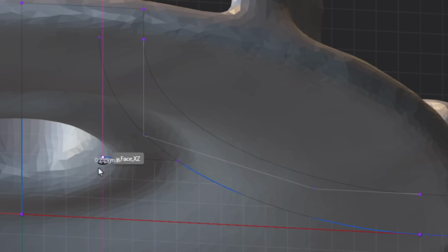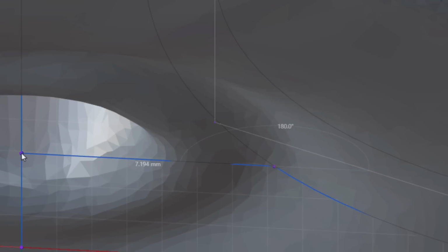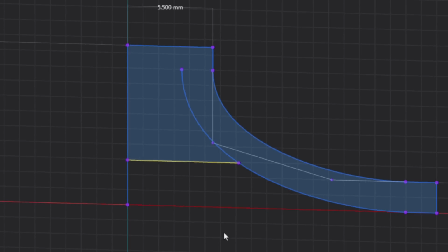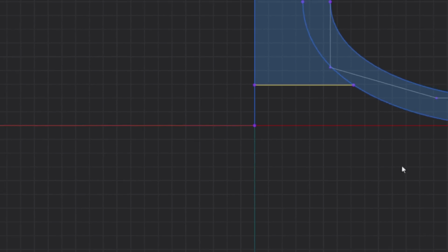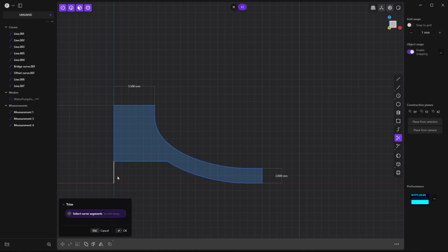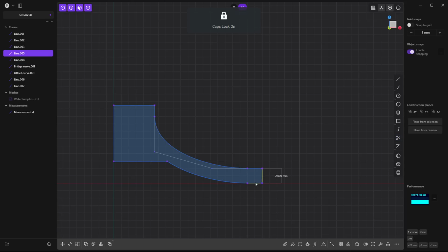So I'm going to go to about there, and let's go ahead and do this one more time. So find that position where we want, let's say here, and we're going to come all the way to this point. It's saying closest, we'll right click and accept, and then we'll hide the impeller. The reason I did that is, again, we're going to be going back and adding the hole after the fact. So now we can use our trim tool, which is T on the keyboard. We can trim that away, trim this away, right click.